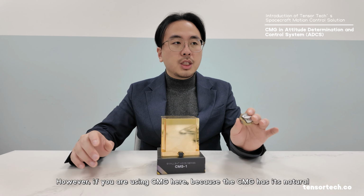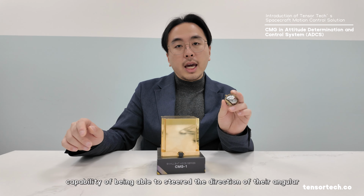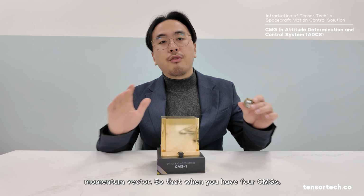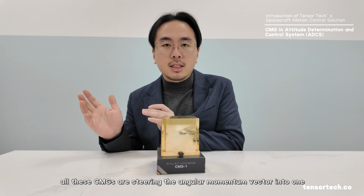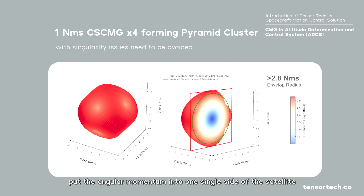However, if you are using CMGs, because the CMG has the natural capability of steering the direction of its angular momentum vector, when you have 4 CMGs and all of them are steering the angular momentum vector into one single direction of the spacecraft, then you are able to put the angular momentum into only one single side of the satellite.